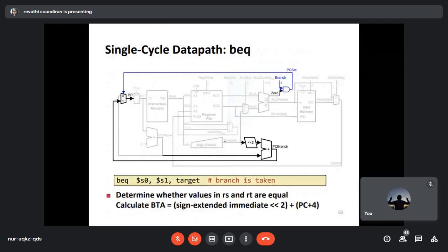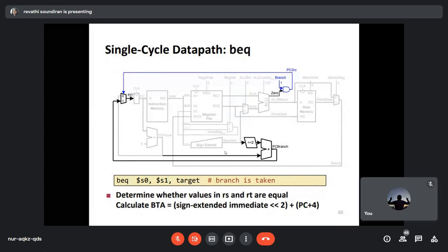So next is your branch instruction. This is typical to your jump instruction. If you want to perform branching, you have to know what your current program counter value is, so it will decode the address. The instruction we are talking about is branch equal. So your ALU has to perform whether it is equal or not. This is the logical operation that is taking place in the ALU. It will look at the output, 0, then it is going to branch if it is going to be 1.